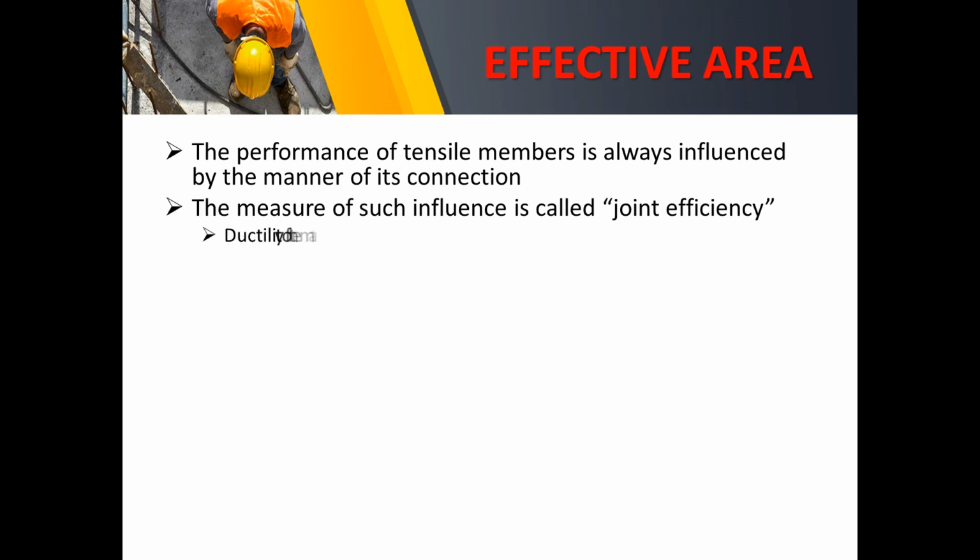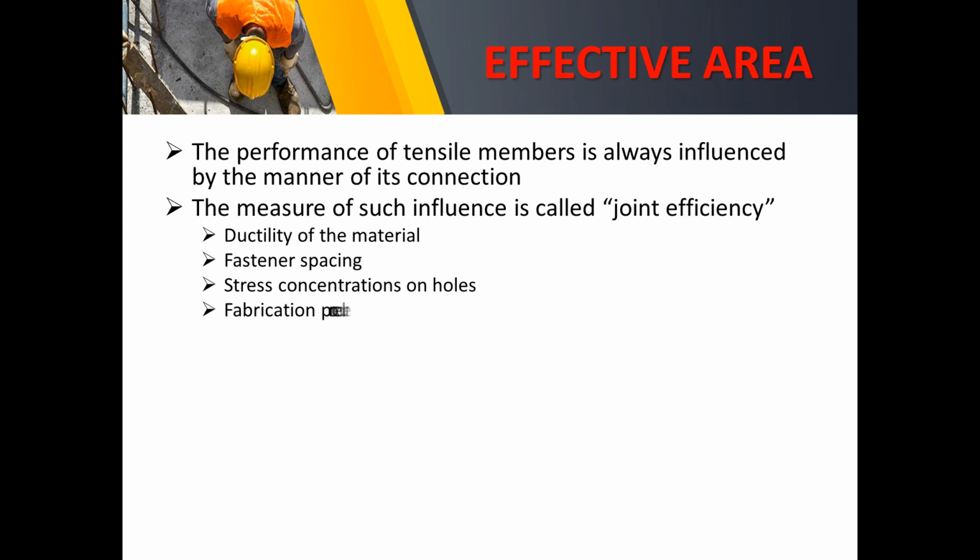So the measure of such influence is called the joint efficiency. It is associated with the ductility of the material, the fastener spacing, the stress concentrations on holes occupied by the bolts, the fabrication procedure, and the shear lag.